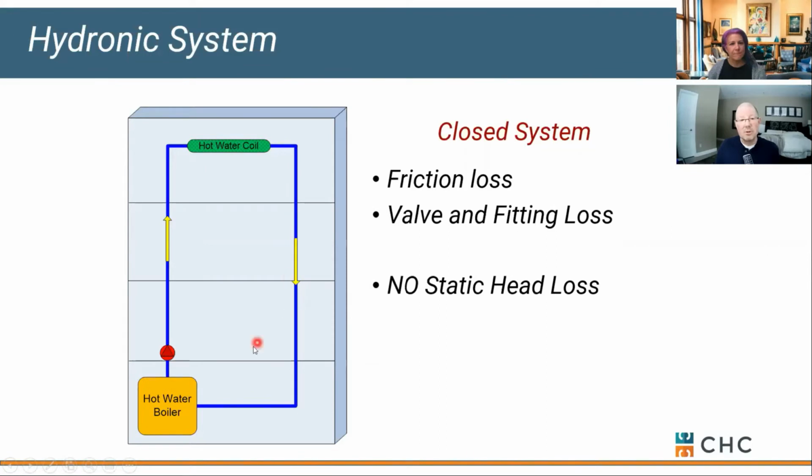As we move water through our closed loop system, now we can turn our boiler on and we can heat it, and we can take that hot water out to some coils or VAVs, heat exchangers, and we can exchange heat. We can blow air across it, or we can transfer that heat to something else in our system. Snow melt is a good example. I'm looking at about 6 to 8 inches of snow out in the driveway. A snow melt system would be really nice these days. But that's a typical closed loop system. Okay, again, what goes up comes down. We don't care if this building is a mile high or a mile long. We just have to make sure that the pipes are full of water. That's very important.